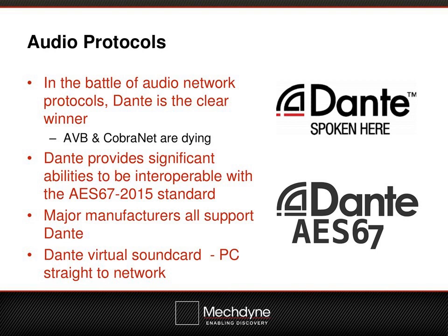Almost all the major audio manufacturers now are going to be supporting Dante. And one of the cool things about Dante is that there's also a Dante Virtual Soundcard. So basically, you connect a PC up to a network, and you have this virtual sound card, and it sends the audio from the PC out directly as Dante over the network connection connected to that PC. So you don't even need to make any other audio connection to that PC.